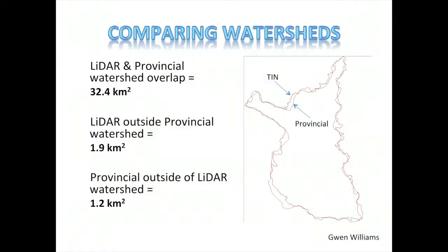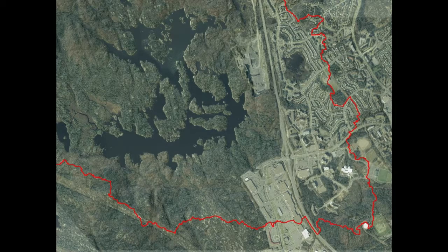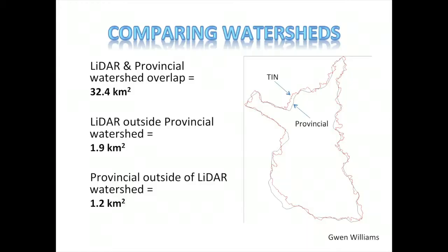I did want to illustrate how if you go to the provincial databases, because this is usually where they reside, and extract provincial watershed layers, and then you recreate a watershed using higher resolution data, you'll very often find slight discrepancies between them. But another thing worth noting is that in urban environments, the watersheds that we might obtain from our database, say the provincial one that we have illustrated here, is going to be the surface watershed.